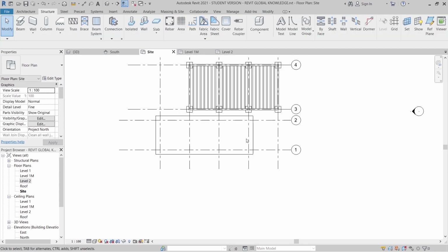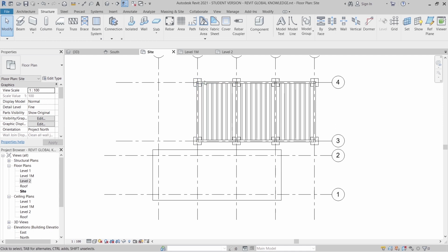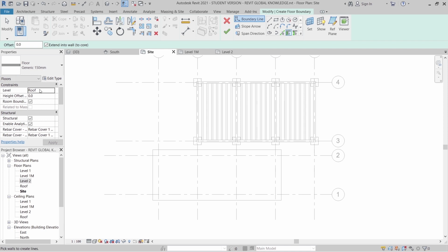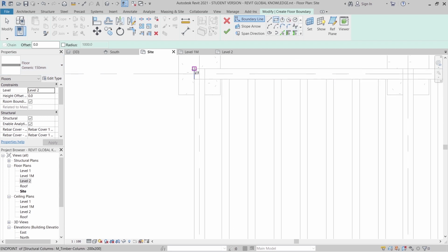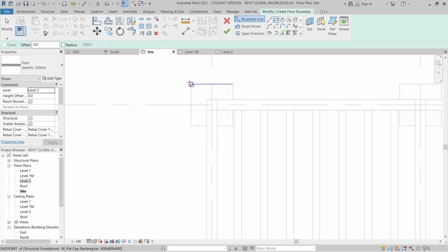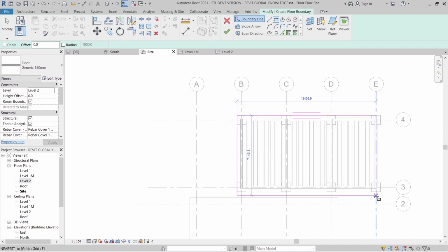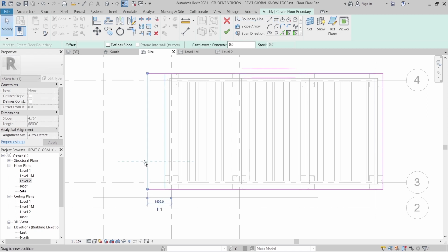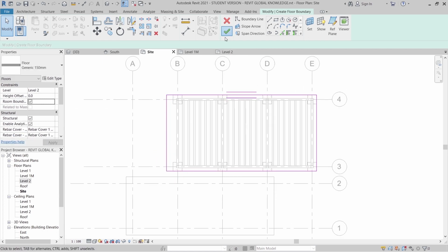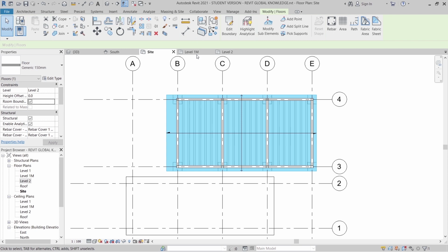For beam direction, I'm going to delete it for slab direction. And need to add another floor there. Go to our structural tab using our floor and change our location level to level 2 and just add our grid. I will just simply add it like this. Escape. Then here I need to adjustment, make it like this for 1 meter for extend. Go to my 3D there.